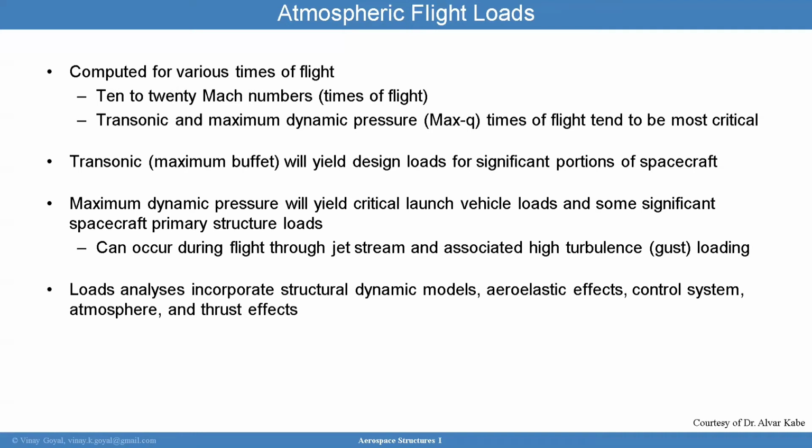You want to calculate these loads, and they're only calculated on the day of launch. Wind velocity as a function of altitude is measured prior to launch by tracking balloons. So you use balloons really to inform the wind velocity. That's why those become important the day of launch.